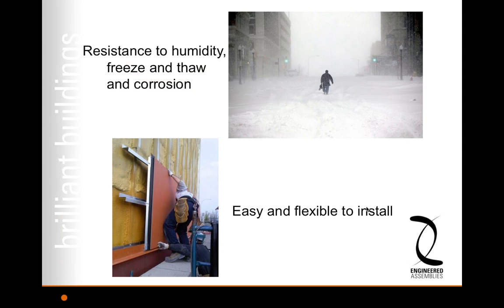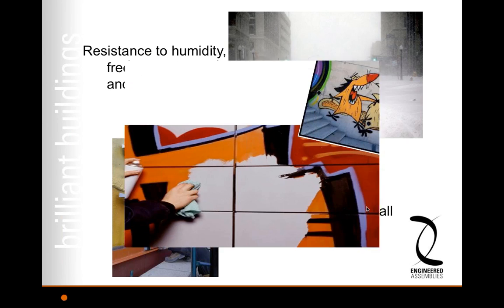day they were putting up. And the holes were already drilled in the panel, girts were up, and these two fellows were just flying like the wind as they plied these panels, because the panels are light and strong and very durable. And so the fastening system was very, very rapid. And in fact, I'll show you the picture, I think, a little bit later. The wall on this grocery store curves 90 degrees across the backside of the building, and the fiber cement panels are able to take that curve.